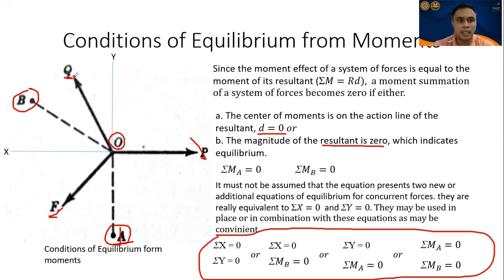So here, class, Q of Y passes through the y component, so it passes through the moment center at A. Also F of Y, the component of F on the y-axis, still passes through the moment center at A. So they have no perpendicular distance. Their perpendicular distance is equal to 0. Okay? So only the x components remain, class, of force Q or force F, the Q sub x or F sub x.